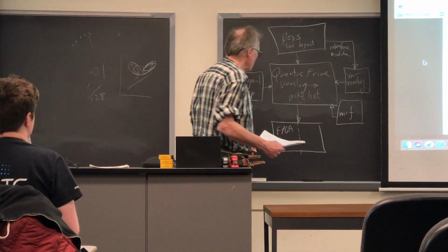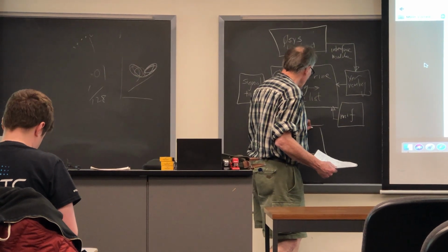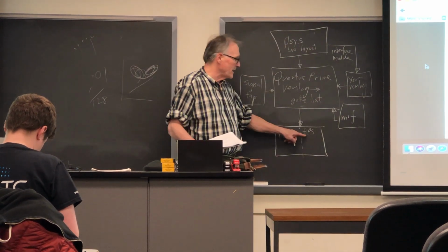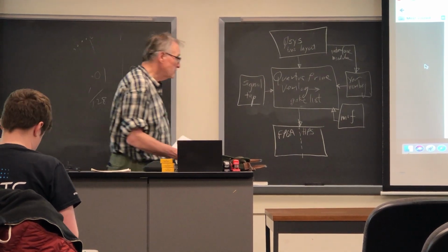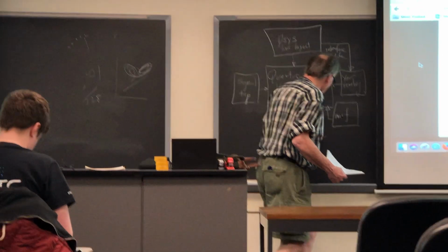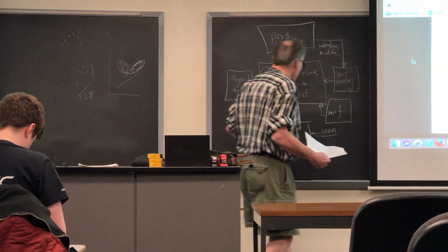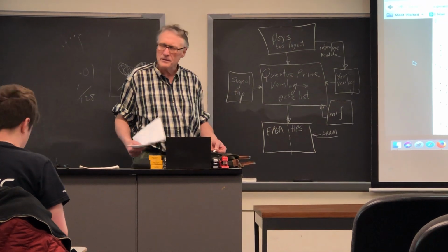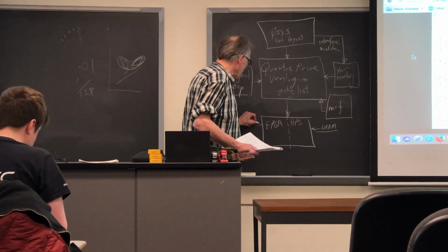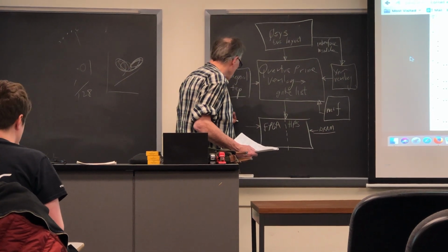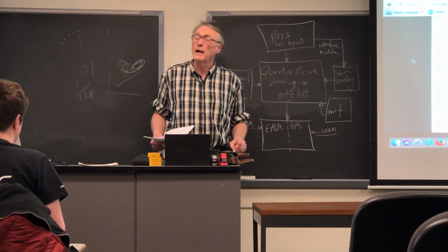Then the output of this is going to get blasted off to the FPGA, which for logical purposes I'm going to separate into the FPGA side and the hard processor side, the ARMs. The ARM has DRAM associated with it, about 1 gigabyte. That's managed by Linux. You don't mess with that too much. The FPGA has DRAM associated with it, which you can use any way you like.